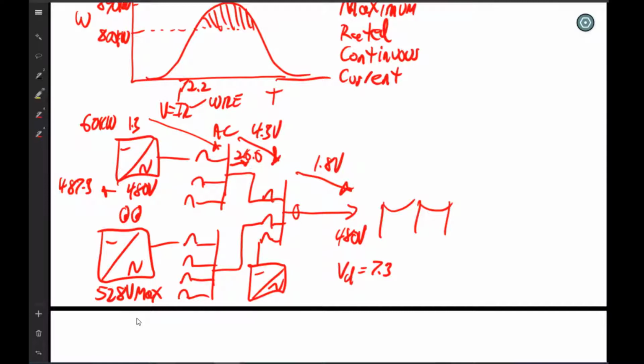So you have to keep your voltage drop below that 10%. Now, I've never heard anybody allow 10%. Most of our customers ask for 2%. The National Electric Code advises basically 5%, and the California Energy Commission requires, I believe, 3%.